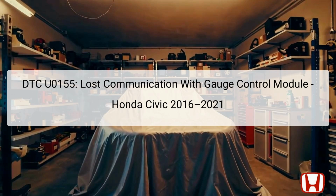Monitoring circuits associated with the F-CAN lines are crucial, as they house essential signals that allow the TCM to function properly. Examining the network setup is fundamental to diagnosing this issue effectively, as it may involve multiple components, including the CAN gateway and various F-CAN connections. Prompt attention to DTC U0155 can avert potential issues in vehicle performance and safety.